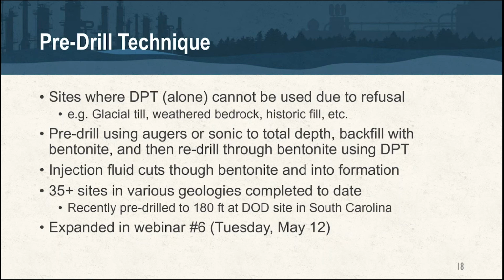And so you're using augers or sonic to get down to your total depth, you're backfilling, and then you're re-drilling it. Now you can use this technology for that because you can think that it's kind of like a pressure washer coming out of that injection tip. Those injection fluids cut through the bentonite and get out into the native formation.